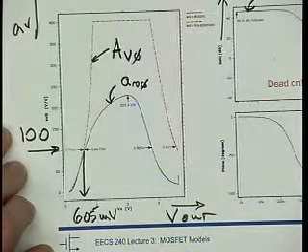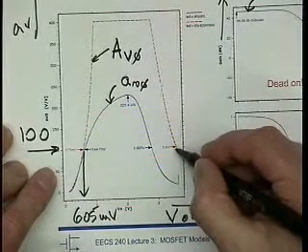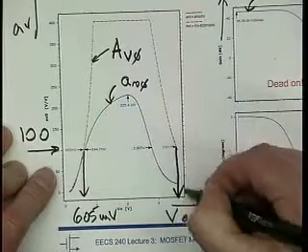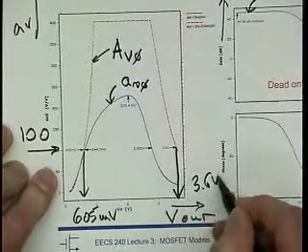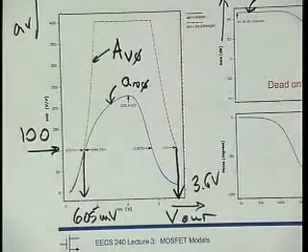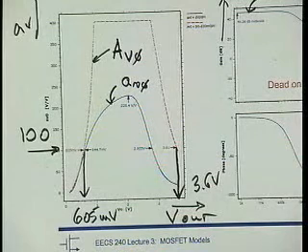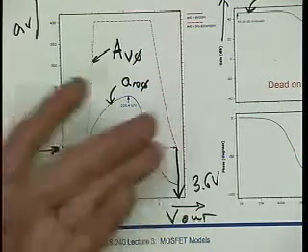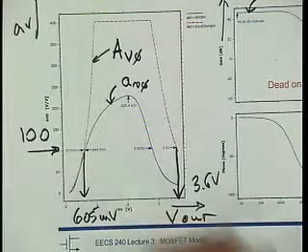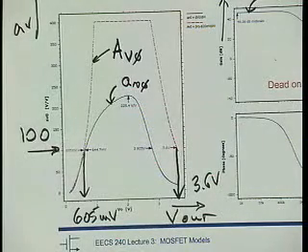And because of this impact ionization story, we don't want to have more than 3.6 volts across our transistor. Well, because the supply is less than 3.6 volts, I guess in this case we don't have to worry about this point, and I just put it there to show you the full simulation.